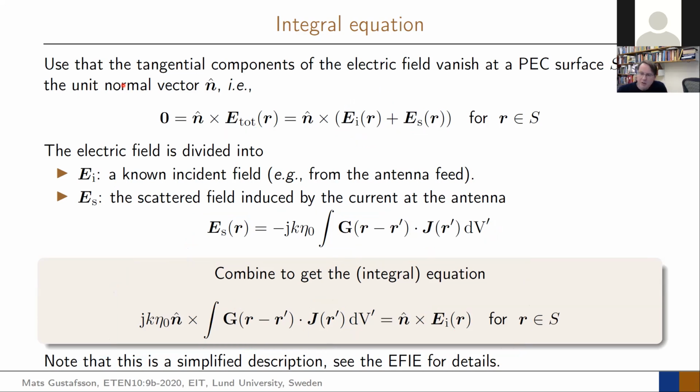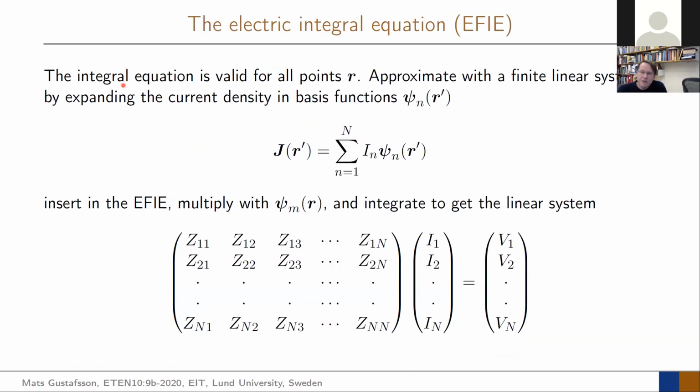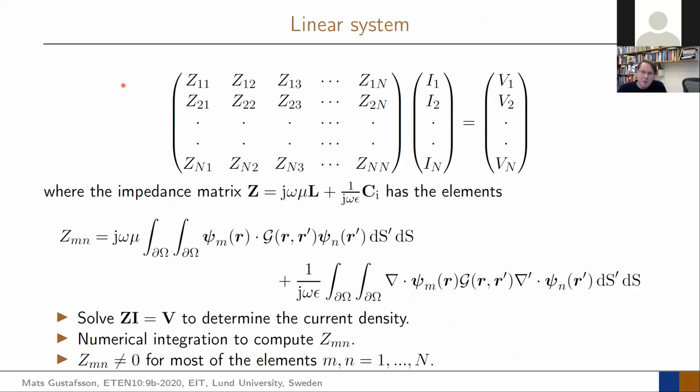And your meshing describes how accurately you're doing this. So you get many current elements here, and an excitation to solve. You have these impedance matrix elements, which come from this previous equation. You have some driven terms to the right, and you have a big matrix. You invert the matrix, and you have solved your problem. The elements are computed inside of FEKO, for example, and they compute these integrals here.